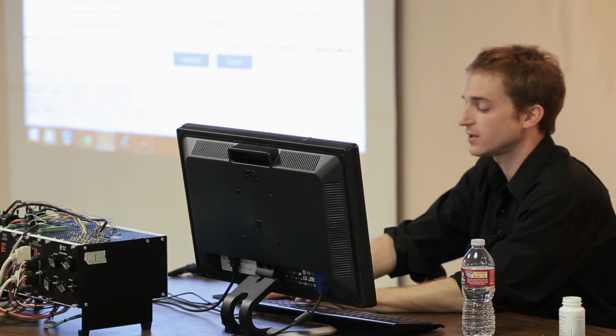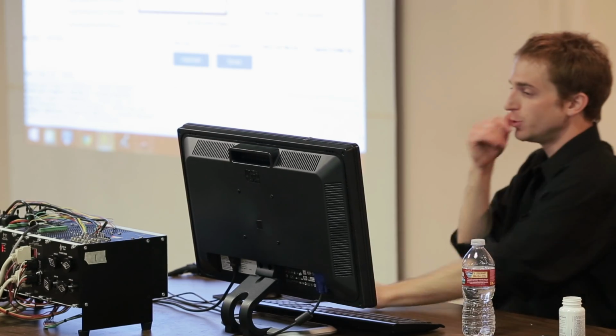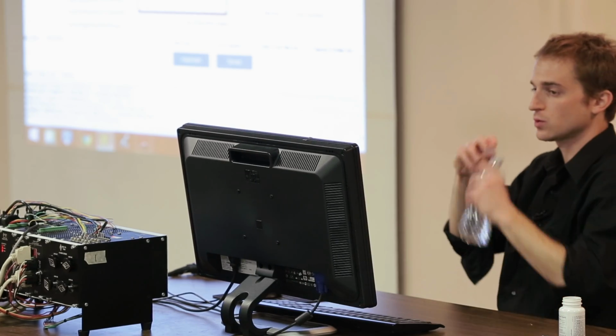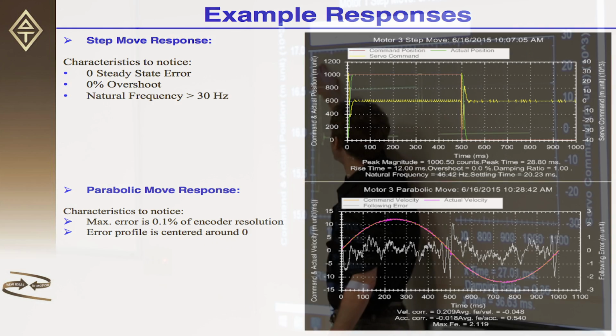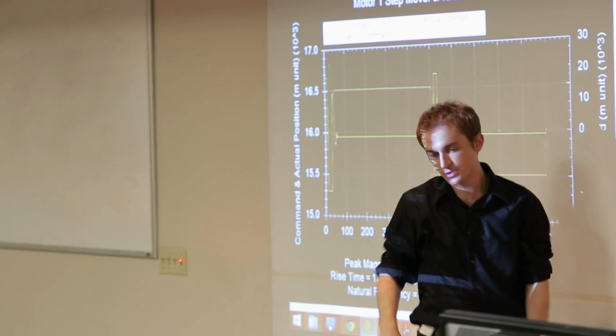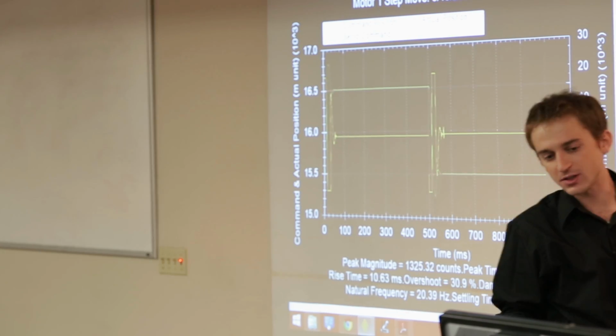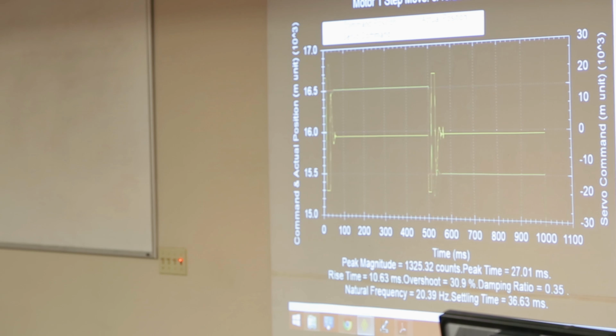But you saw that there was a large overshoot. So I increased KVFB to eliminate that. And now we're at the point where there is virtually no gap. There's still a very small gap, but there's virtually no gap between the resting actual position and the commanded position. But the main problem is we have an enormous overshoot peak, which is for some applications acceptable, for some applications unacceptable. It really just depends on your scenario.